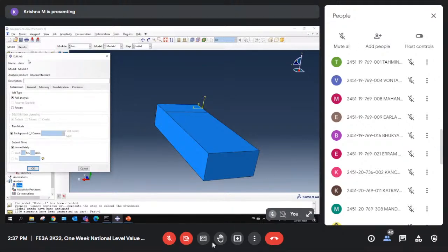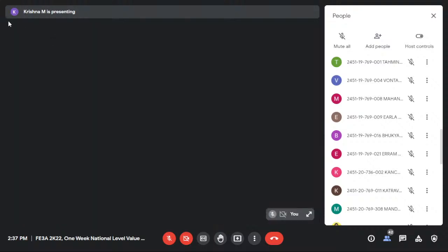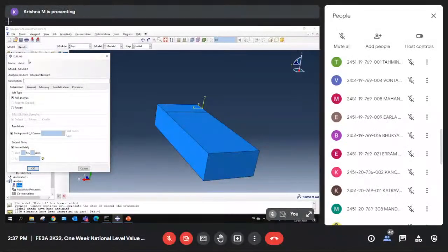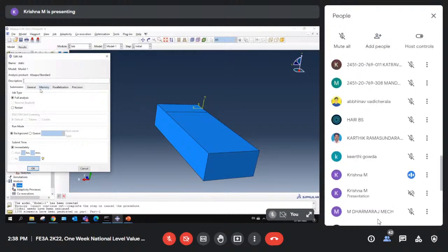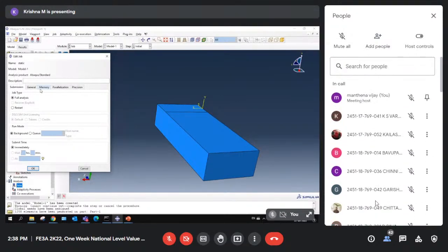So now, before going further to another load case that you have in the list, you want to change the amount of load. So using a restart option, you can change that load and do a restart. So now with the same boundary condition, the job will be started again, and you can continue the job. So even if accidentally, due to power shortage, ABAQUS is closed suddenly, by using a restart option, you can start the job again.